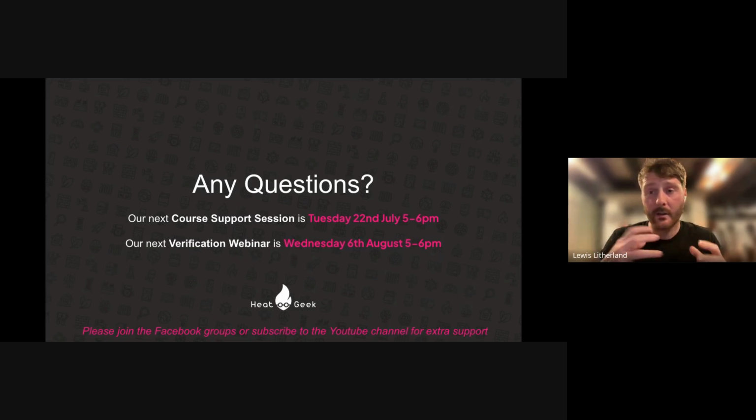Facebook support groups are all vitally important for this kind of stuff. The next course support is on Tuesday. That's going to be pipe sizing. So it starts off with velocity pipe sizing, then it moves on to the resistance side of things, the pressure drop side of things. Put them two together, that's how you know how to pipe size in future. The main thing there is we're trying to work out the index circuit so we can size our pipe, set our pump speed, all that kind of stuff, and balance our system. Really important. And I'll focus a lot more on the module itself, going through that as well, because some of the questions in that I think are really good questions that we'll go through.